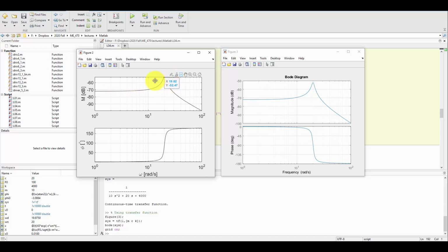We'll look at what point the peak is at on both of the diagrams. It should be essentially the same, depending on how close I got. So we see 20 radians per second is the peak, and again, around 20. I'm not quite at the peak now, I am. So the same omega value of 20 on both of these diagrams.